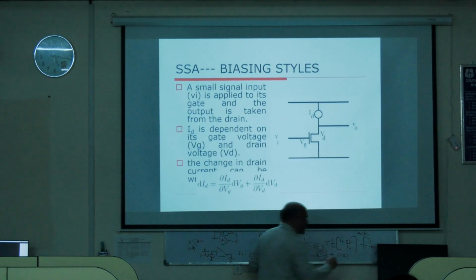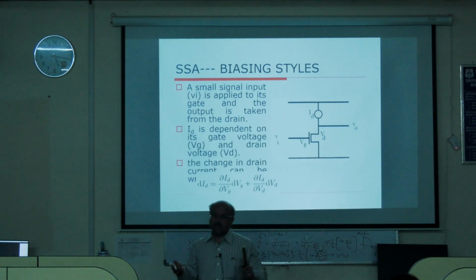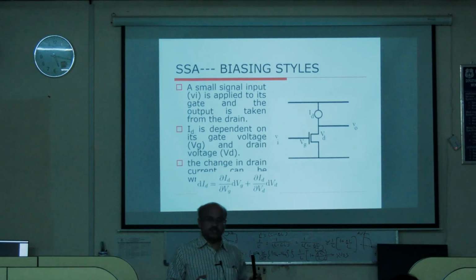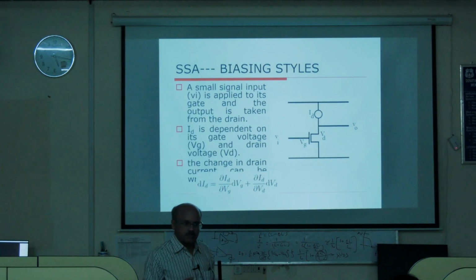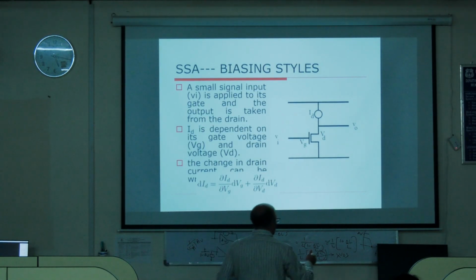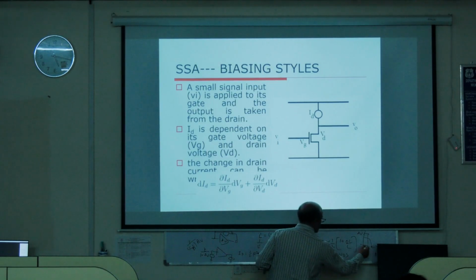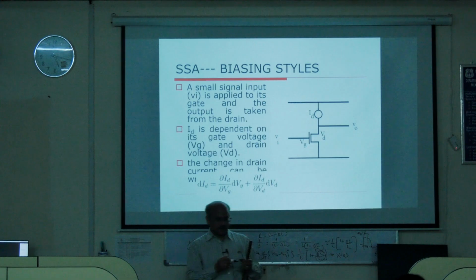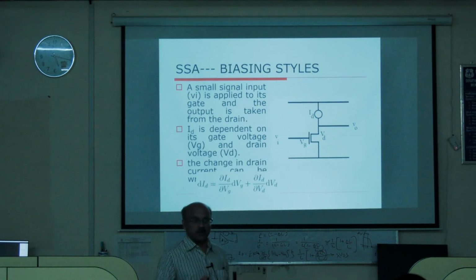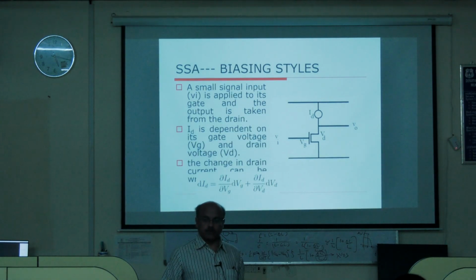So what is happening? This capacitance which it is encountering seems to be large, right? So therefore the corresponding pole moves towards the origin, right? So I can say that this unity gain frequency is coming closer to the origin. So the available gain bandwidth is decreasing, right? So the larger the gain, the smaller the bandwidth, right? So therefore for this given technology I can't improve anymore.